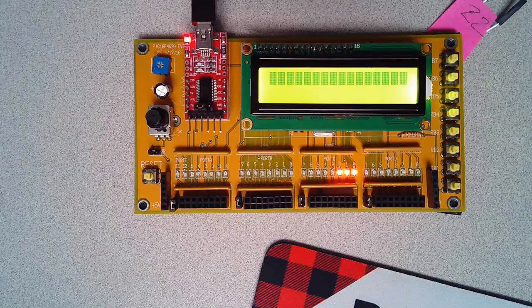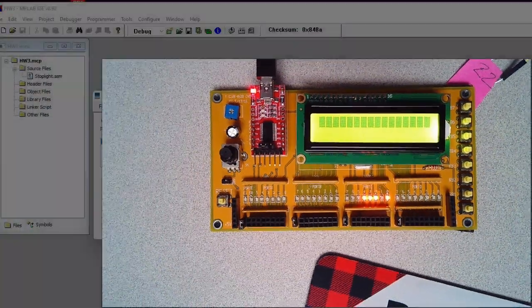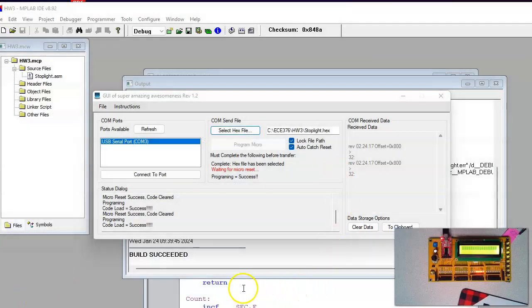And actually when I did this first time, it just locked up. If there's a mistake in your count routine, like I don't have the counters being initialized right, I can get an infinite loop. Infinite loops show up as you hit reset and it just stares at you. It's locked up somewhere. Fix all the infinite loops, get it to be 1 second, and I should get it to count once per second. Okay, so at this point, I now have the wait routine working.